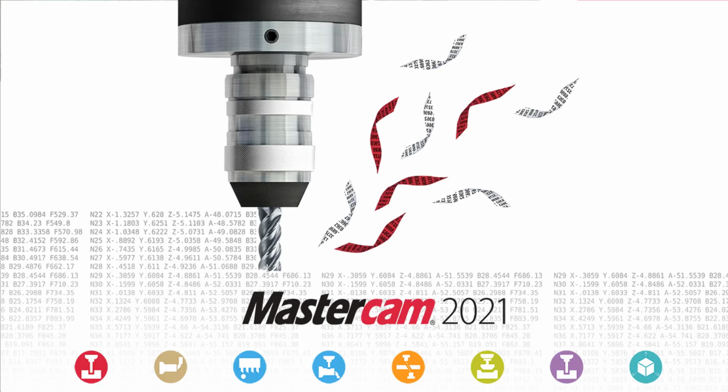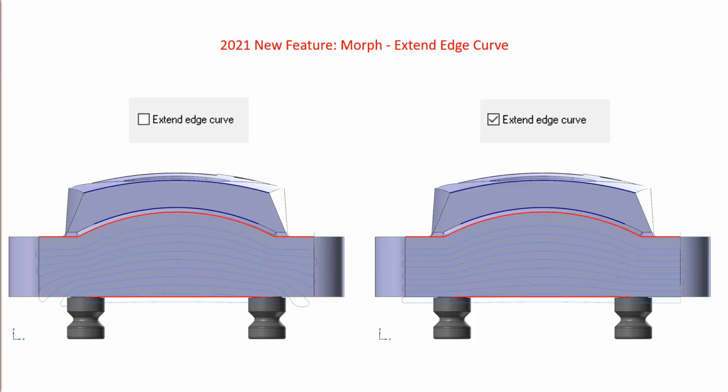Next section here we're going to take a look at is the extend edge curves in a morph. So we're going to look at another part here and look at some extensions and then see how these can help us in the morph tool path. So I've kind of showed you this picture previously, and this is what we're specifically going to talk about when we have a morph 5-axis tool path and we're morphing between this red curve to this red curve. We'll see if they're not even, they drop off, and our tool paths get really kind of terrible on the ends here unless we extend them out manually.